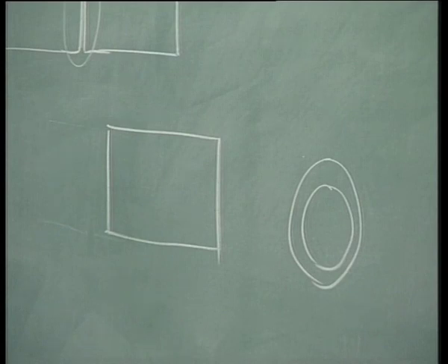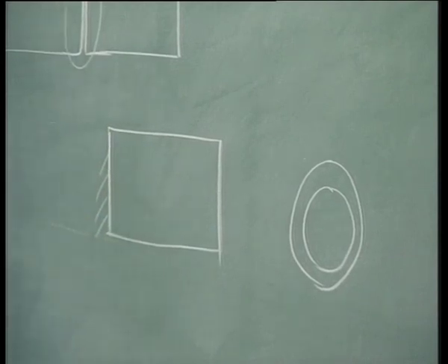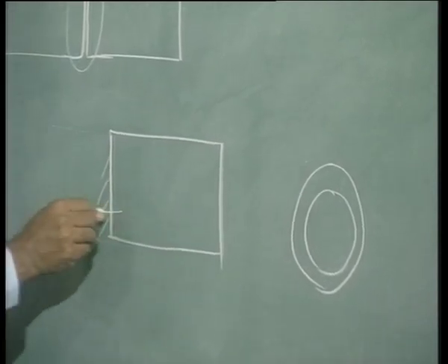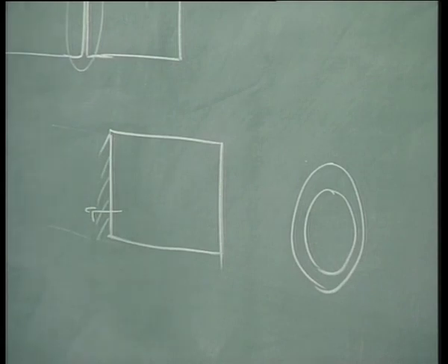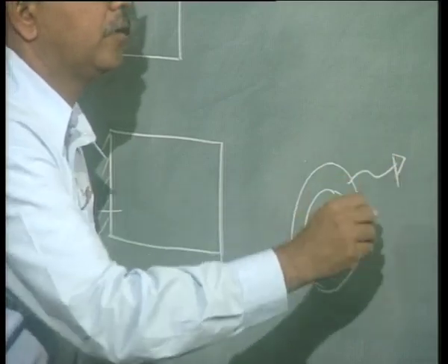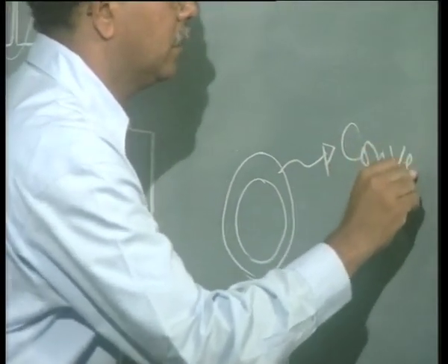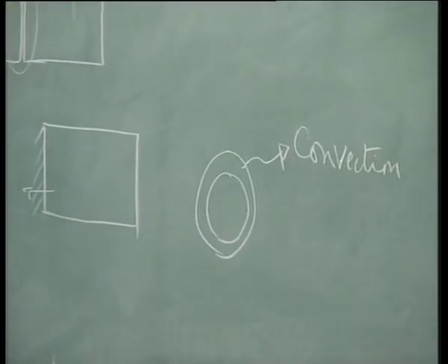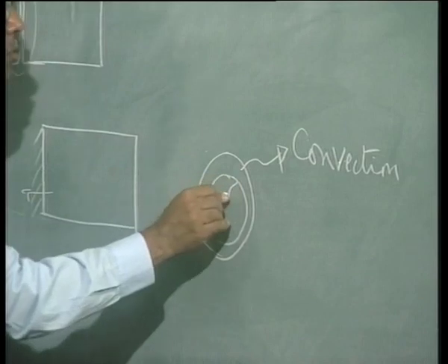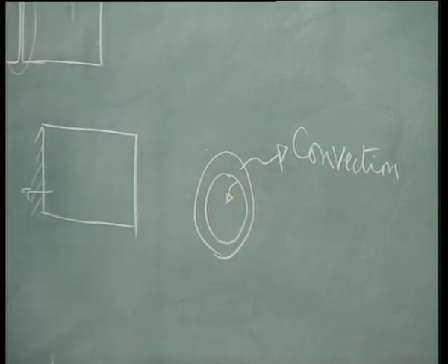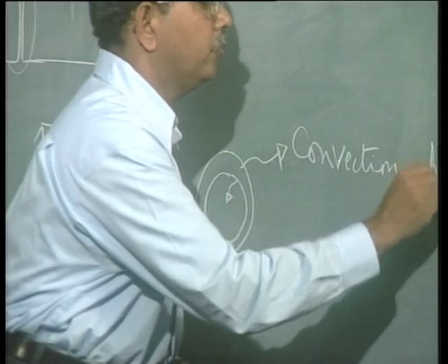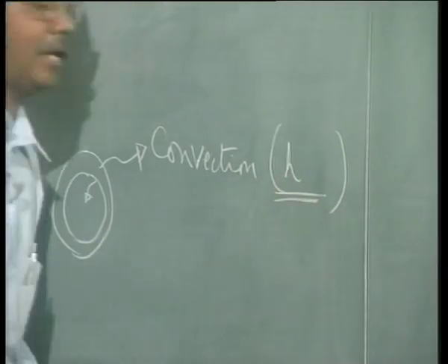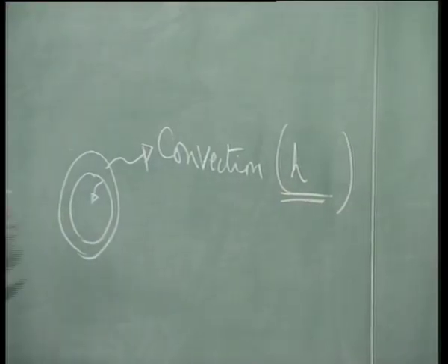Thermal boundary conditions were very clear because we said that we can put that there is no heat transfer perpendicular to it, this side is insulated, okay, and that the heat transfer takes place from this through convection, okay, and that since the pipe is large you can also include convection from inside, though the H value would be different. Note that H value would be different from the top as well as from inside, okay.